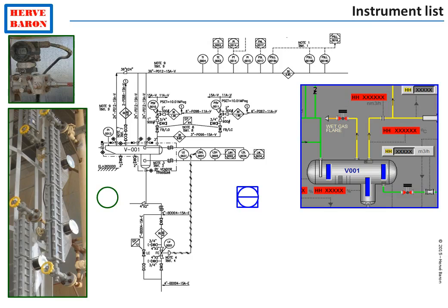The starting point of the discipline is the P&IDs. On the P&IDs, process has shown all instruments required for monitoring, control, and shutdown. For monitoring, process also specified if the measurement shall be locally available or available remotely from the control room.